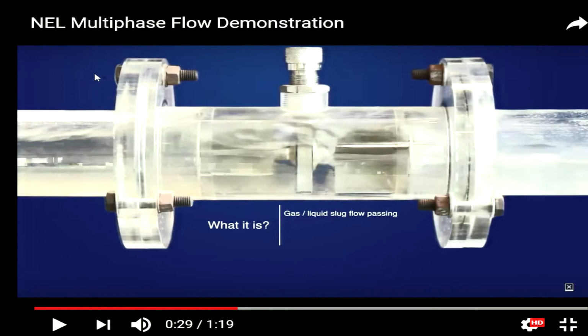PIV. Well, for PIV to work, you need access to the complete flow cross section, right? But you have lots of bubbles in between. So the bubbles will mess up your PIV autocorrelation function.